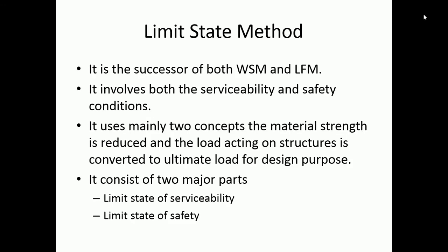Next method is the limit state method. This is the successor of both the working stress as well as the load factor method, and it involves statistical procedures. Based on that, we have an approach called the probabilistic approach, and we'll be having two major parts in the limit state method. One is the limit state of collapse, and the other is the limit state of serviceability.